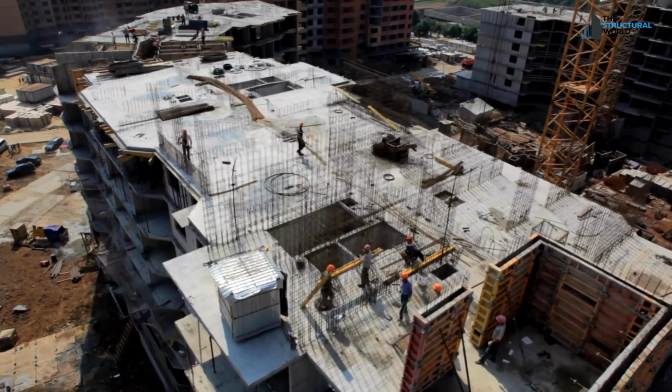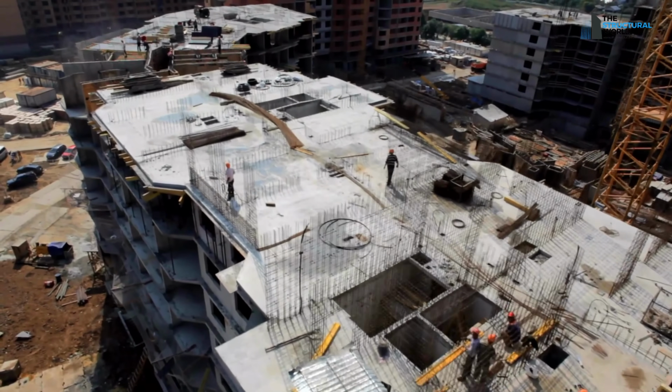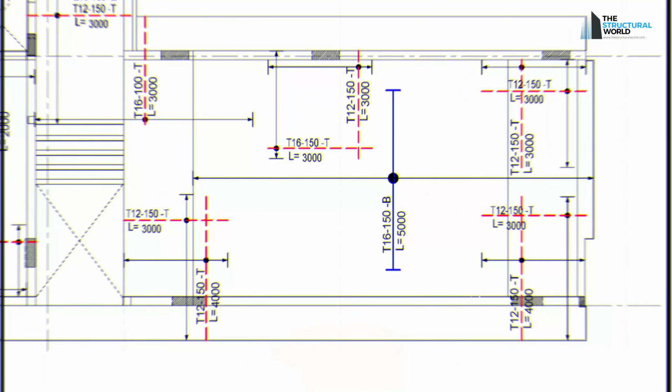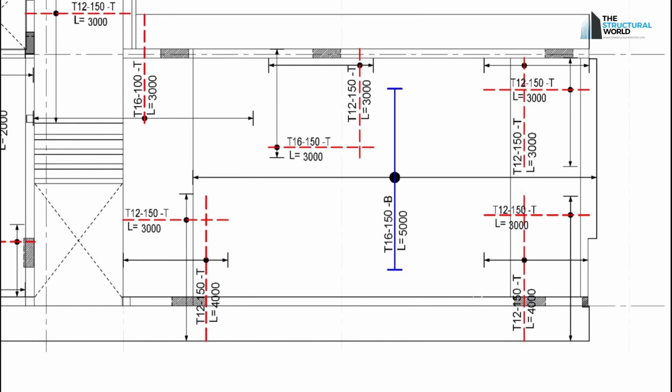When dealing with flat slabs, similar with raft or mat foundations, the drawing is a bit different because the reinforcement arrangements of extra bars, whether top or bottom, are shown on the plan directly. In this arrangement, you can see the orientation of it and an arrow indicating the directions of laying. The rebar diameter and spacing are also indicated with the schedule of the main mesh reinforcements of the said slab.